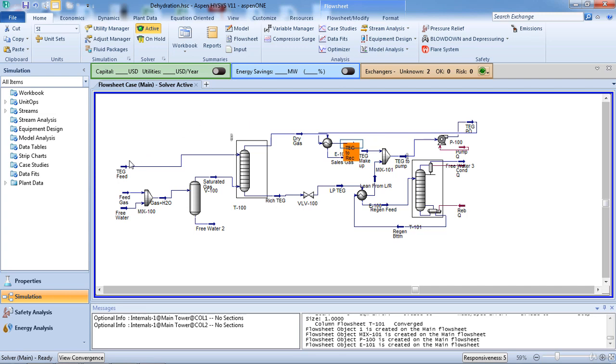If we redefine the triethylene glycol feed to be exactly like the triethylene glycol to recycle stream, HYSYS will recalculate all of that, and you will find a new composition for the glycol to recycle stream, and so on. So this will not be the suitable solution. What can we do now?